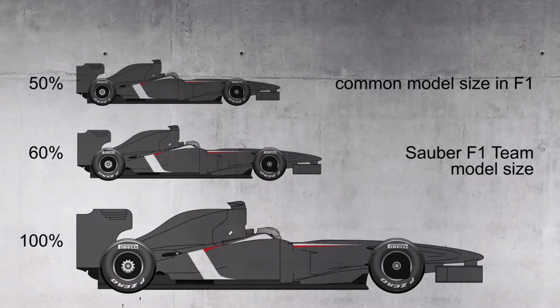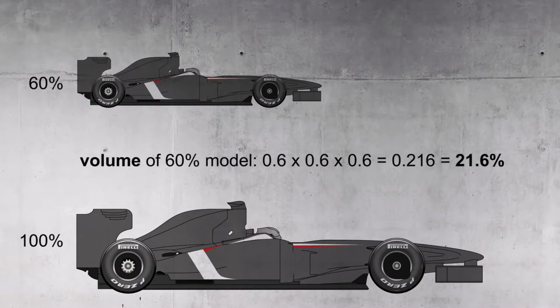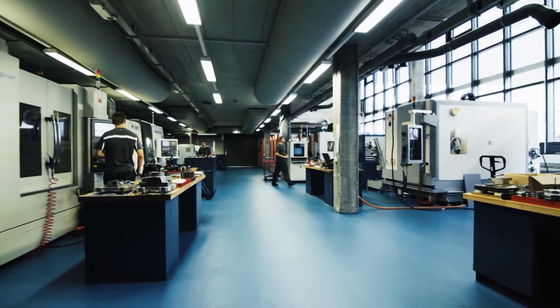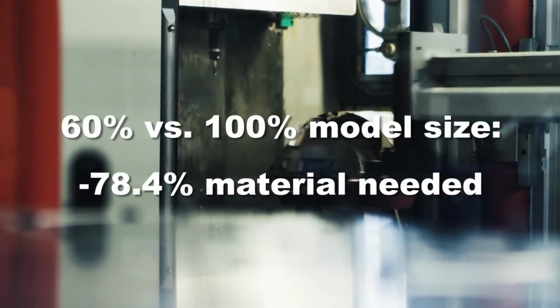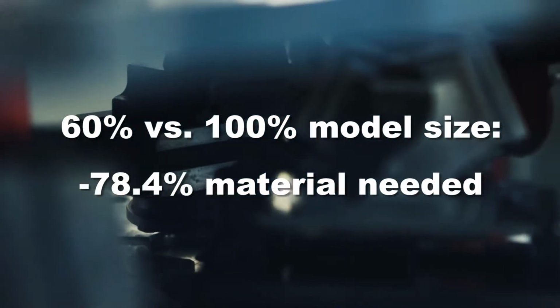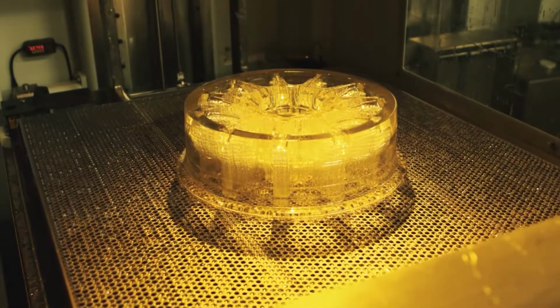Now, for a 60% model, the volume of material that you need to make the parts is 0.6 times 0.6 times 0.6, which is, in percentage terms, about 21.5% of the volume you'd need if you're making a real part. And the same applies if you take a block of material that's the right size for machining a part from, say, a block of metal, then the same rule applies to how much metal you have to remove from your block. So the cube of the scale, that 21% for a 60% model, relates quite closely to the cost of making parts. So model testing costs you much less to make the parts.